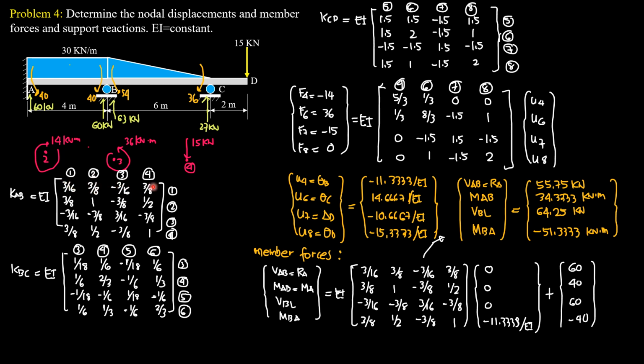Then you just copy 3/8. Then the next row would be 6 EI, 6 times 1 over L square, 4 square, 3/8 also. So you just copy that. This is 4 EI, 4 times 1 over 4, so that's why 1. This is the negative of this value here. And this is 1/2 of this 1 here. 1/2 of 1 is 1/2.